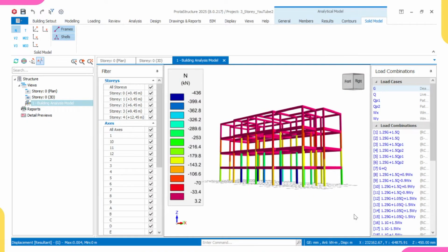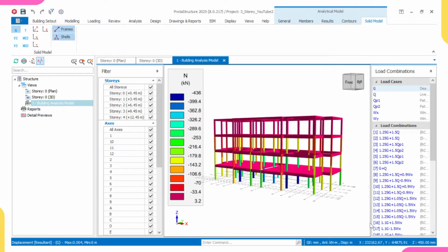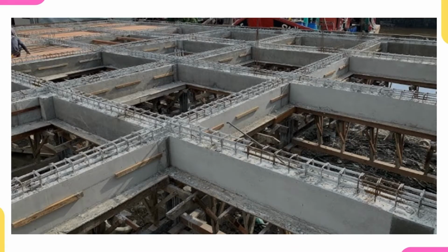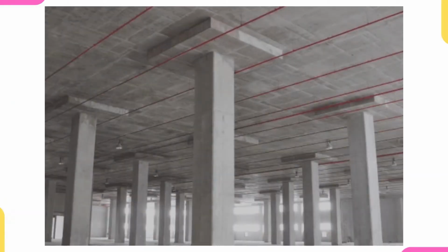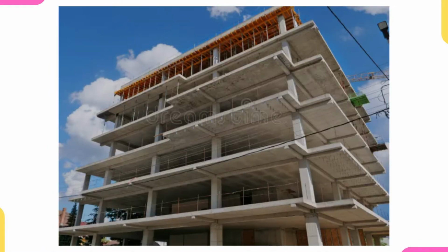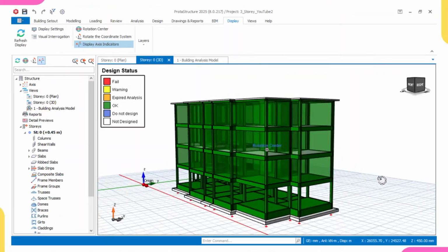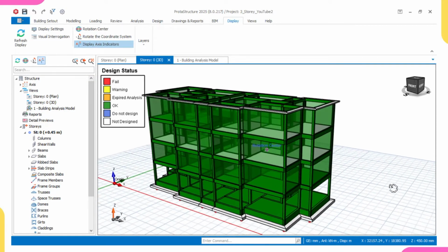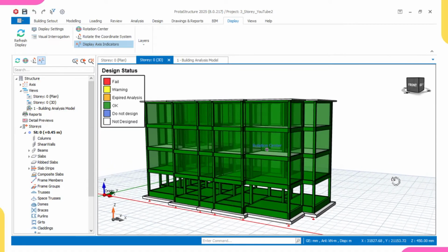I will be showing you the governing principles in structural framing, some of which are: limit your column spacing to 6 meters to avoid excessive moment on the beam and save cost, minimize point load acting on beams, and finally, keep your slab panel under 30 square meters in area to prevent deflection. Structural framing is totally dependent on the engineer, but the engineer has to follow the governing principles while carrying out his structural framing, and those governing principles are what I'll be exposing in this video.